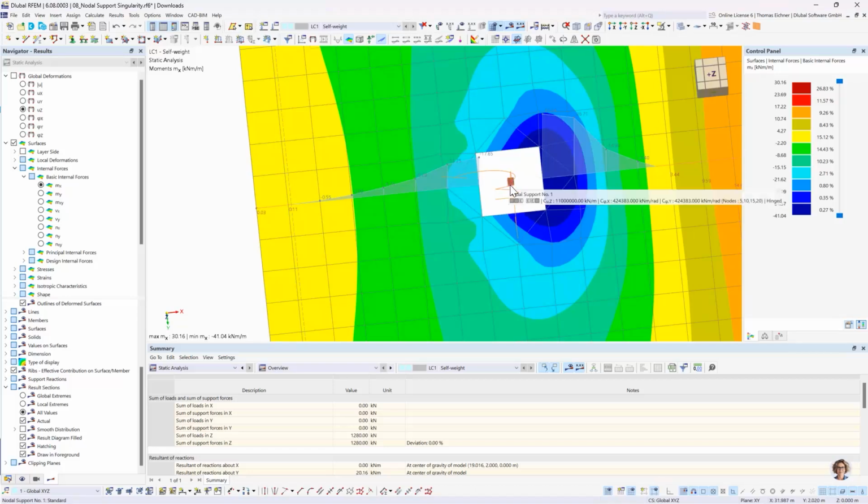So the problem is the pointy force must develop over the space. So right now, if we try to apply it to this rectangle, we would have a pretty big area it could go to. But the smaller these finite elements get, the smaller the area the force can distribute around.